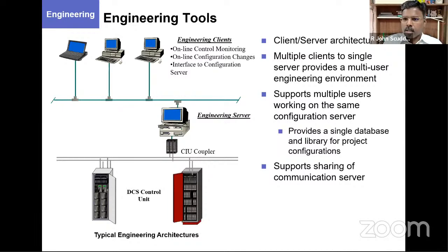The operator workstations are the graphical human interface. The engineering station is the logical human interface. For the logics which are inside also, you need a human interface, but as core electronics and instrumentation people, especially you who are listening to me, you will be core involved in these engineering stations, where the logic needs to be interpreted in a way that computers will understand, and the control philosophy given by the equipment manufacturer is all put inside. Then our ultimate aim is to give everything to the operators, the operation engineers, who will be graphically, visually seeing the things and then doing it.